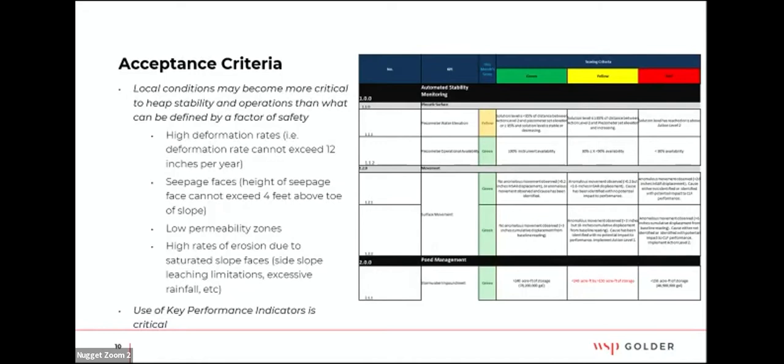Do you limit the rate of deformation that you're willing to accept on this leach pad? You end up going through the heap and doing effectively a risk assessment as to what you are willing to accept in terms of rates of movement or amount of pore pressure, rates of rise of pore pressure. You might not have exceeded your overall factor of safety in an area, but you're getting rapid pore pressure increase.